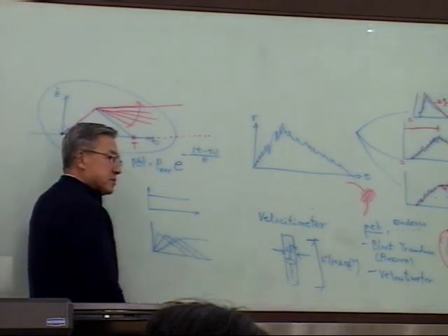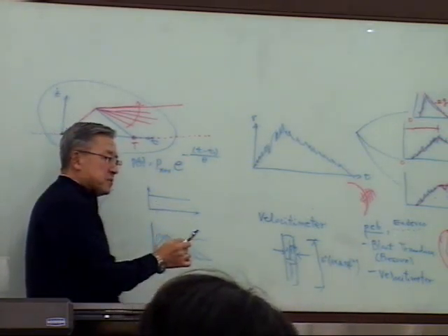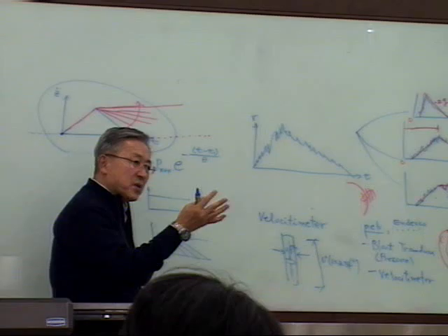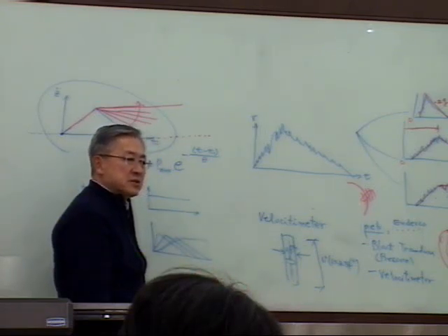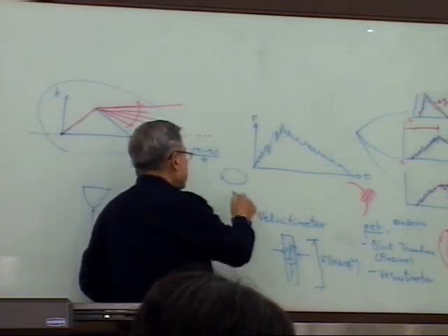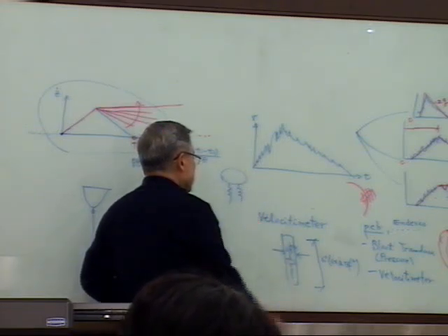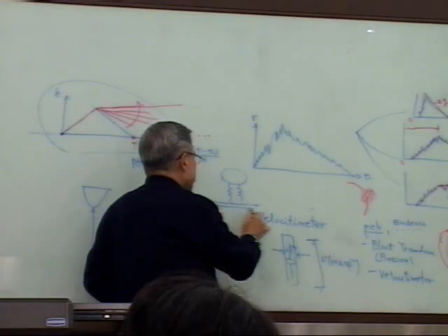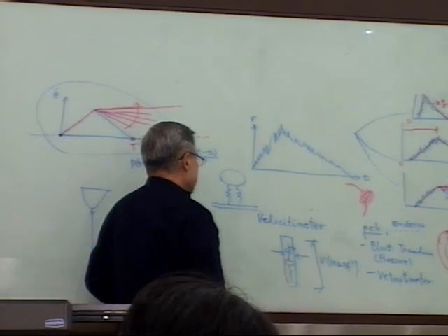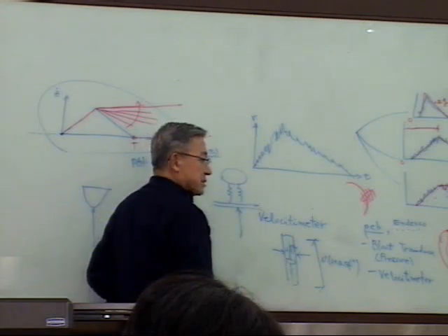So as you look at the input excitation waveform, the input excitation for shipboard equipment is always the base excitation. Because you mount the equipment with springs, which means some support structures, put it on the deck, or put that on the shell, wherever, the excitation is coming from the bottom.